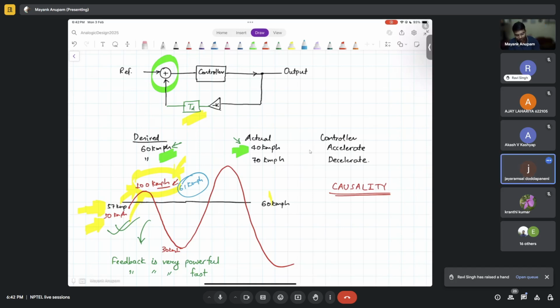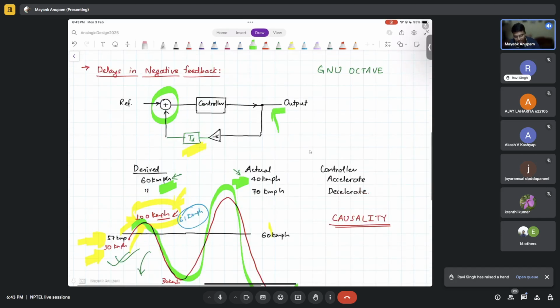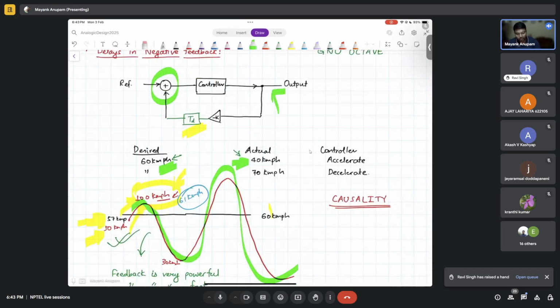Yes, basically ringing at the output, exactly. And what can happen in this particular example is that this ringing will never stop. In fact, it will keep on increasing. You understand the behavior, because you are a very aggressive rider; you take extreme decisions. If you translate it into a controller example, we say that the loop is very strong and very fast. That's what we mean when we say that the rider is very aggressive: the system has a feedback loop with a very high loop gain, and it is very fast. Got it?